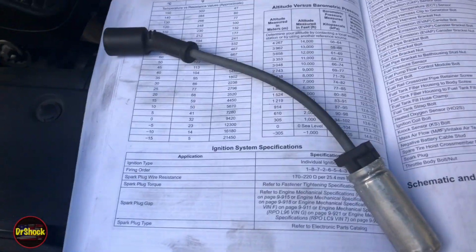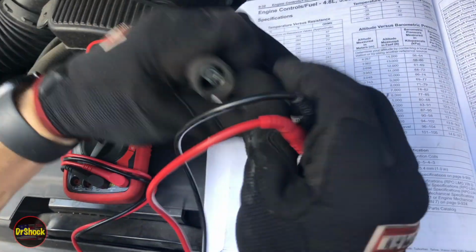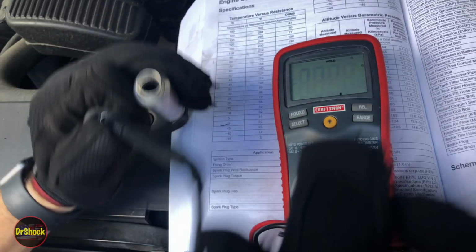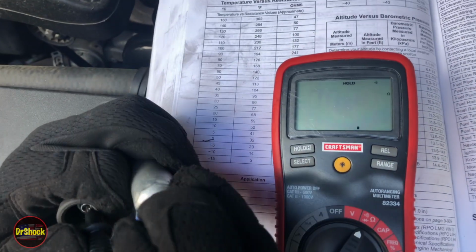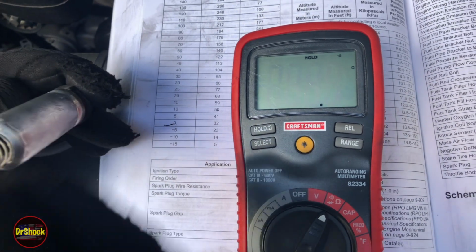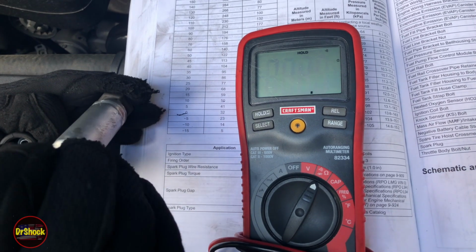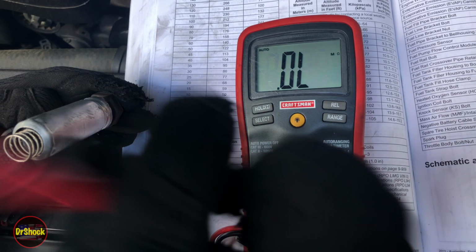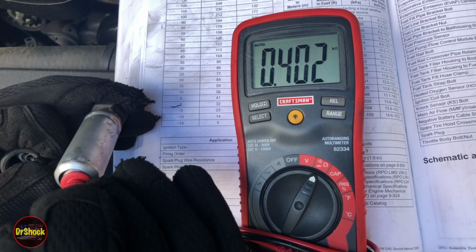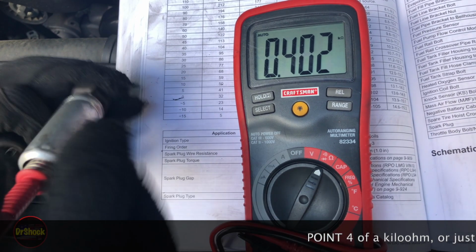So let's see what we've got here. Real simple, we're just going to come in here, push our spring down and we're going to make contact here. If we can make contact here, way deep inside, might need to get an adapter on my probe here. Let's get this in the right mode. There we go. What do we got? 402 kilo ohms. So that is not in spec.